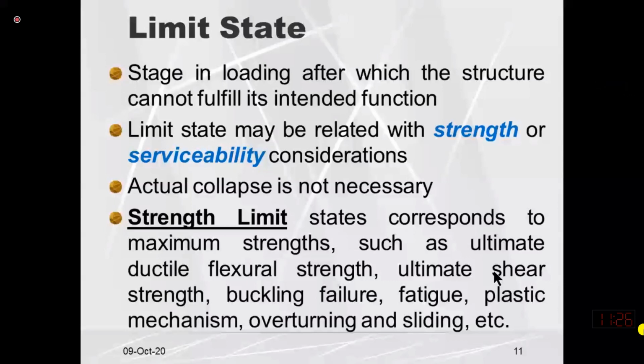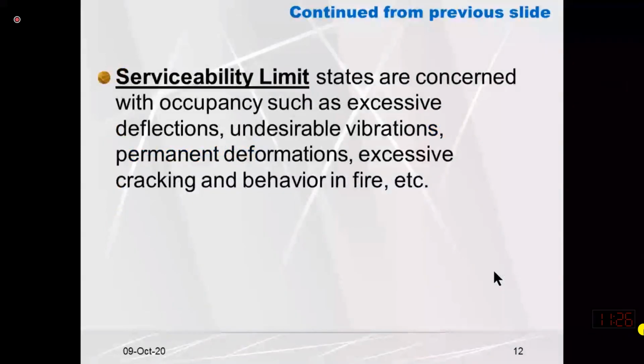Serviceability states are concerned with occupancy, such as excessive deflection, undesirable vibration, permanent deformation, excessive cracking, and behavior in fire. For example, in a beam we have an allowable deflection.